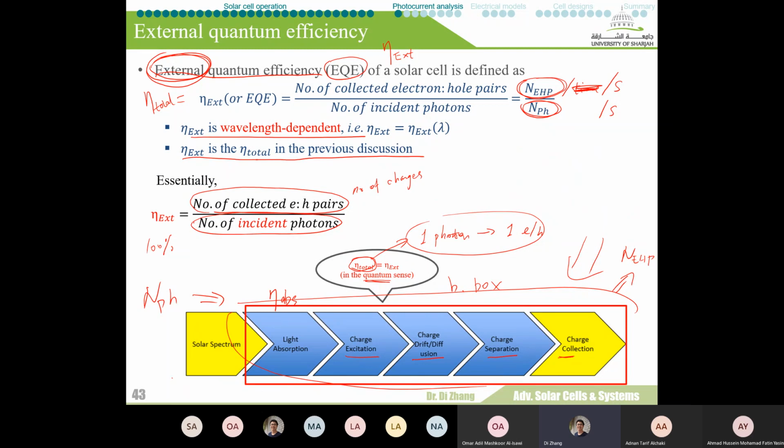Okay, you can only say that this solar cell has maybe 60% quantum efficiency at this wavelength, but at other wavelengths, we are expecting the quantum efficiency will change. We are expecting the quantum efficiency to always be a function of the wavelength. This is different from the energy efficiency, because typically for the energy efficiency, we're talking about the energetic efficiency under the AM 1.5 spectrum.